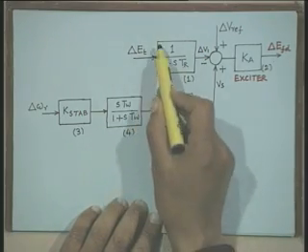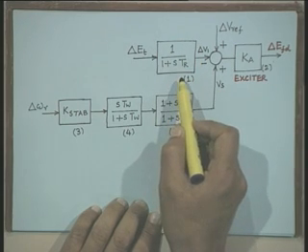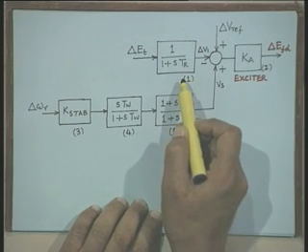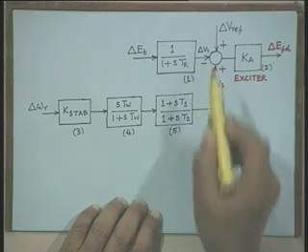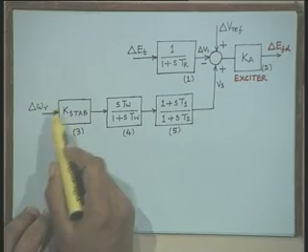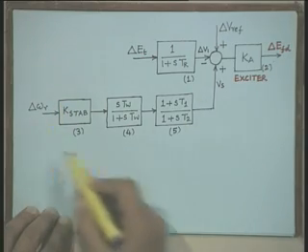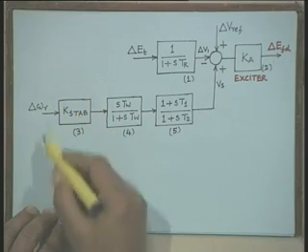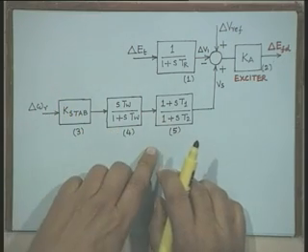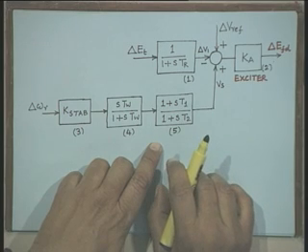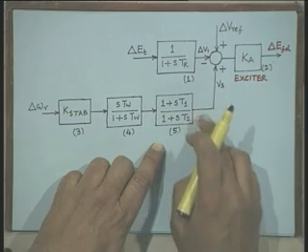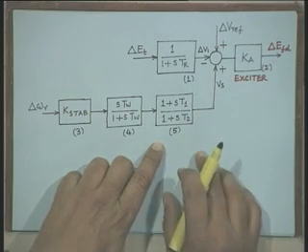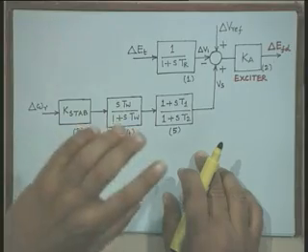This is the change in the terminal voltage, delta Et. This is the transfer function of the terminal voltage transducer, which gives a quantity called delta V1. This is the transfer function model of the PSS. I have shown in this model a single stage phase lead compensator. If necessary, one can put one more stage, a 2-stage phase lead compensator, and accordingly you can modify your state space model.